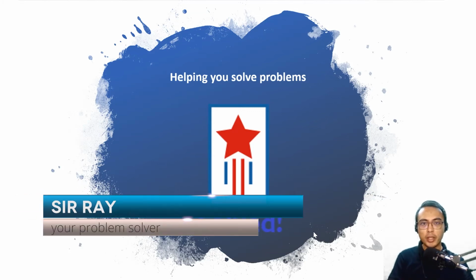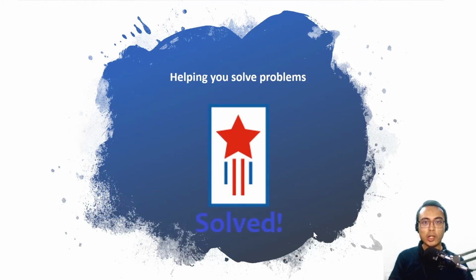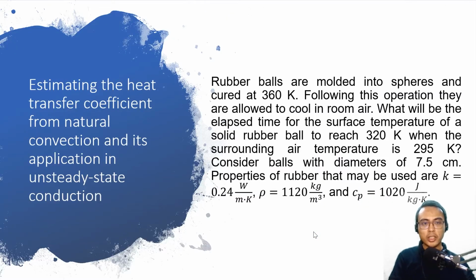In this video, we will be discussing the solution to a natural convection system coupled with unsteady state conduction. So let's begin with the problem. Rubber balls are molded into spheres and cured at 360 Kelvin. Following this operation, they are allowed to cool in room air.